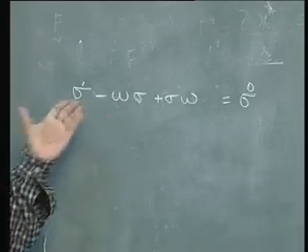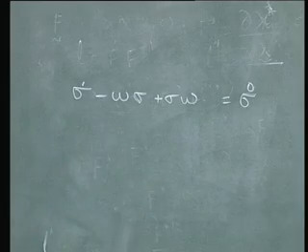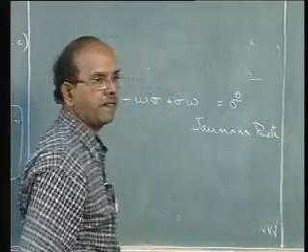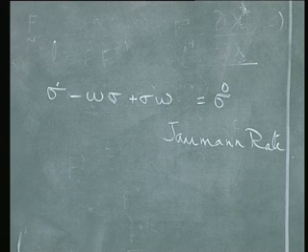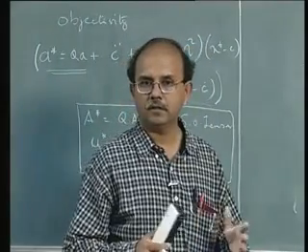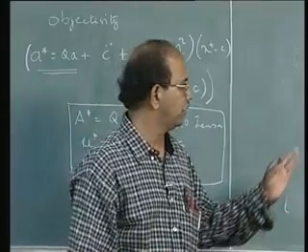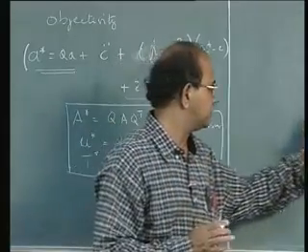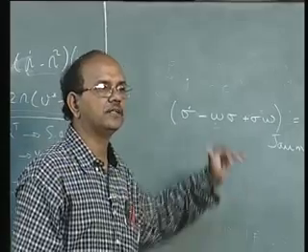What you have to do is only substitute for w what it is. But before I complete it, let me introduce this. This is called the Jaumann rate. Jaumann rate is extensively used in large deformation plasticity. You can see it mentioned in packages like Abaqus manuals. So what does Jaumann rate mean? Since sigma dot is not objective, a basket of sigmas and dots is taken together, and that is used as the rate quantity, so that the quantity becomes objective.